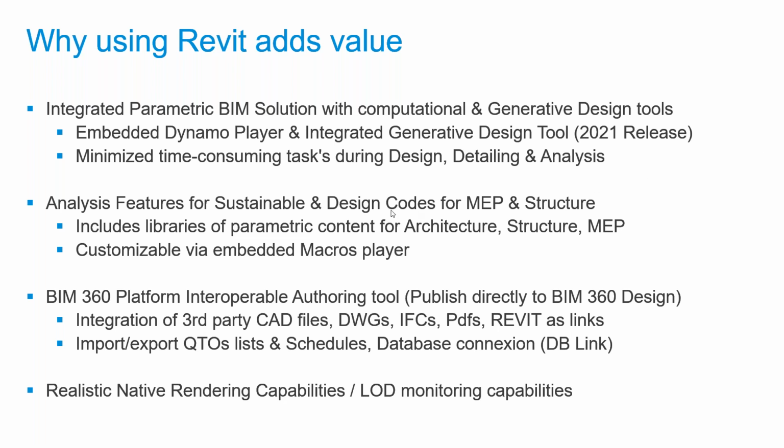And I should mention that we have some questions coming in about how you would get a Revit file into Plant 3D and a Plant 3D file into Revit. There are a couple of different things we probably need to address here. There is no live link right now between Revit models and Plant 3D.